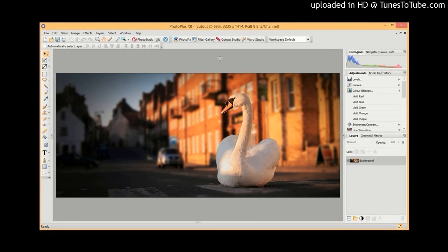So we want to start marking areas to keep. We'll switch to the Keep Brush tool here, and then click, drag over areas we wish to keep. Now, because this is quite a complex subject, we want to make some quite fine adjustments. So what we'll do is take the grow tolerance down to a smaller value, such as 20. And this will ensure a more precise result.